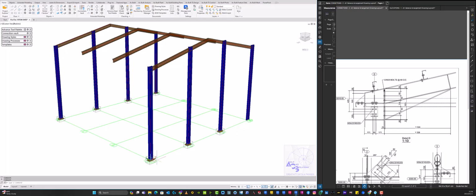So at first it copied with the connection, remember, because it's not connecting to any other steel section. We just added a base plate to a column. So it will copy if you copy the base plate and the connection as well. But let's say it's a beam to column connection, and you just want to copy the beam and the connection. The connection might not go to where you want it, because remember, you have left another element, which is the column. So bear in mind there.